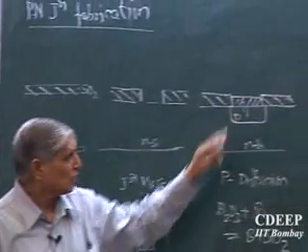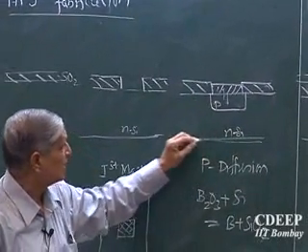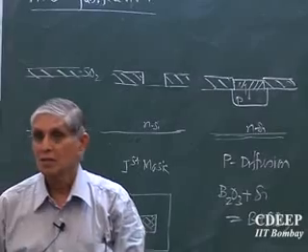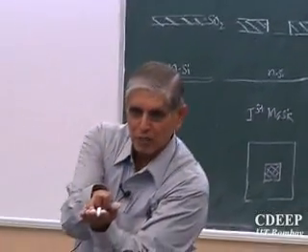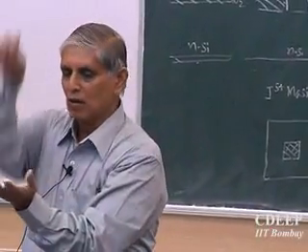But since I don't need that contact on the side right now, I remember there is no oxide here now. I open during this, and I will also have another oxide here. The wafer is kept like this, the mask is placed on the top. Light is always vertical, so when the light is shining, nothing happens. And there is no resist on the back side. Resist is only on the top. Is that correct? So the lower oxide is always there, but when I etch the upper oxide, the same thickness of oxide will go from below when I etch it.